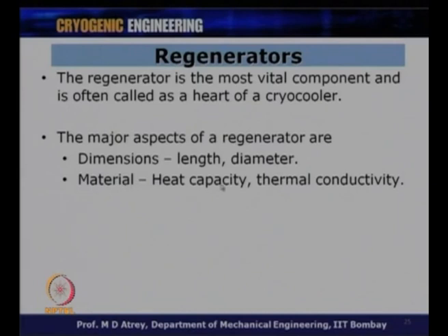So, this is going to decide what is the lowest temperature that could be attained by this cryocooler, because at that particular temperature the regenerator will get saturated. That means it cannot take any more heat from the gas, the matrix gets saturated. So, this is a very important aspect of the regenerator.